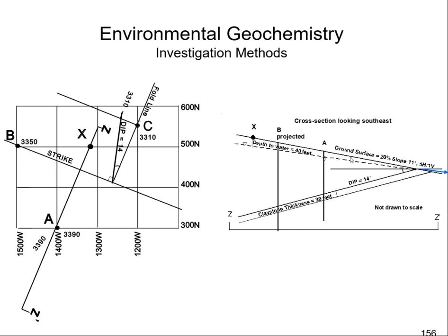So I draw my depth to water in here, and the question asking where, first question 57, is where you're going to find the contaminants in the unconfined aquifer. So that means this space here above the claystone layer. And that space, if this was a DNAPL, which it is, that question is kind of asking two things.